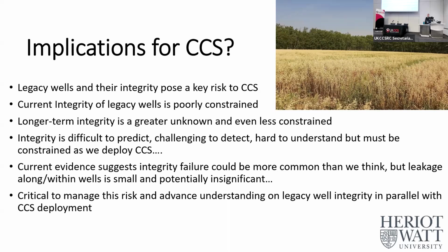Basically, for me, looking at this for quite some time, we really don't understand all of the ins and outs of these legacy wells. We don't know how commonly leakage occurs. We don't know why. Longer term integrity is an even greater unknown. So even if a well's not leaking now, what happens in 50 years, 100 years, 1,000 years? Do we start to see leakage, and how does that play into it? Overall integrity of these wells is difficult to predict, challenging to detect, and hard to understand, but we do have to try to enable these CCS projects to go ahead with minimal risk.